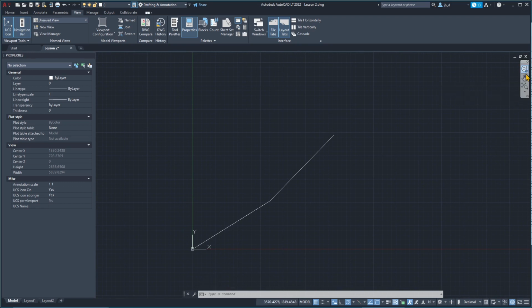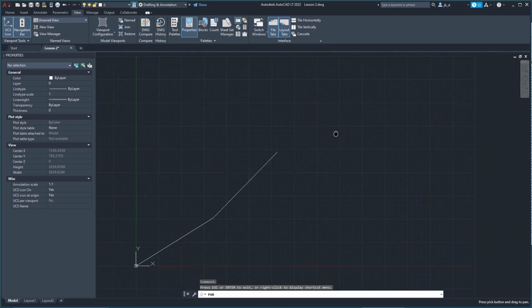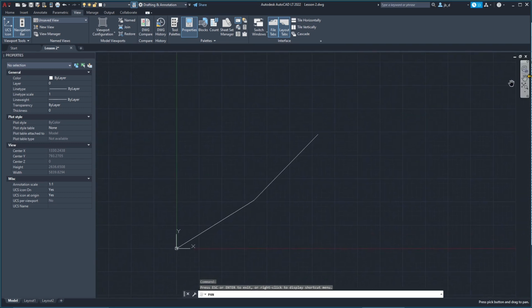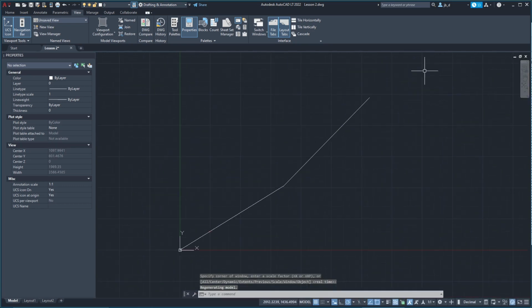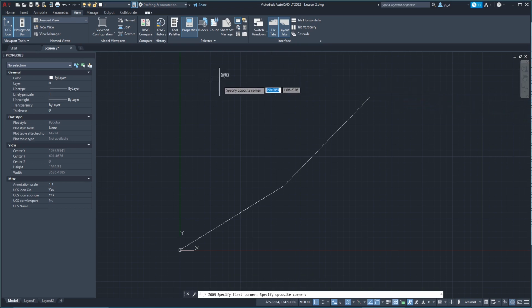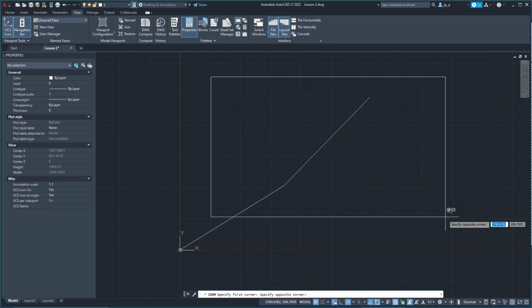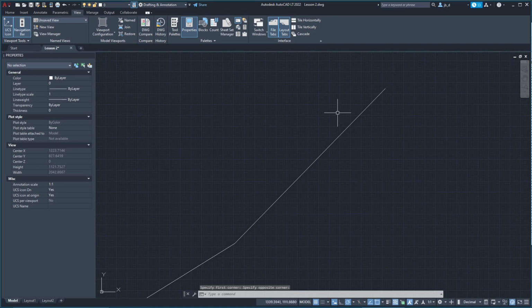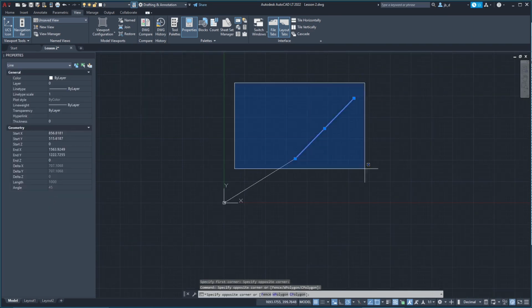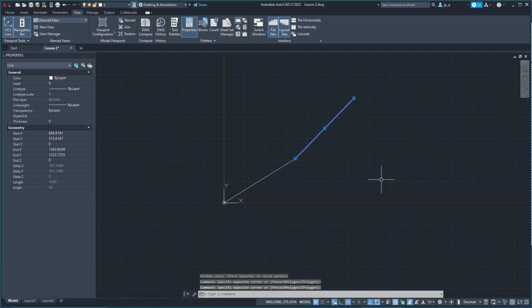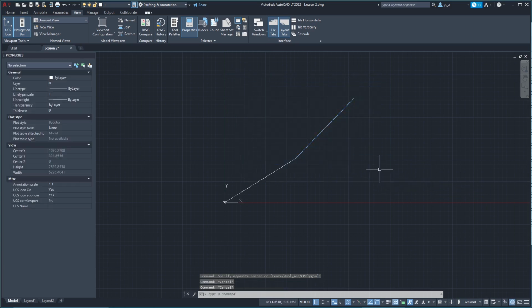And well, we find again the pan, so we can use it from here. And then we have a couple of extra zooms, like zoom extents, which is going to show you the extents of your work. And then you have zoom window, so you're going to create a window by clicking one time and two times. It's kind of selecting like this or this. Now we're going to talk about selections a little bit more.